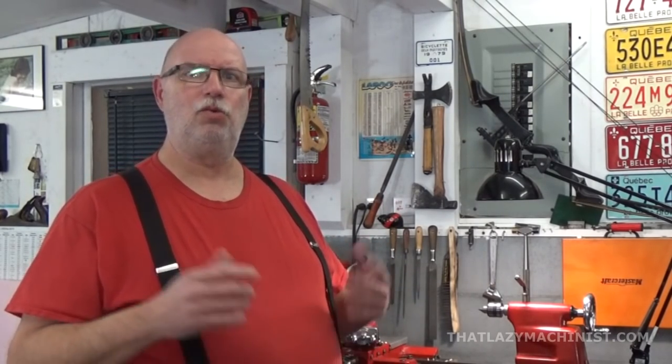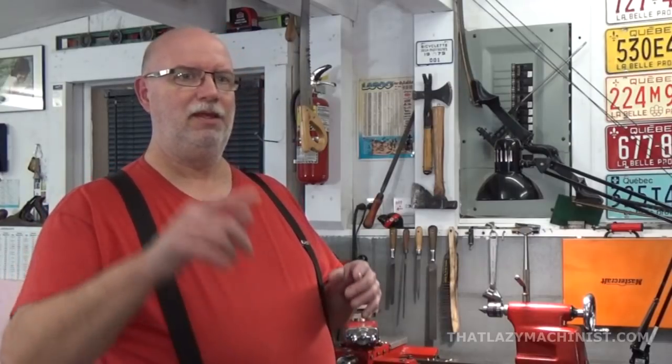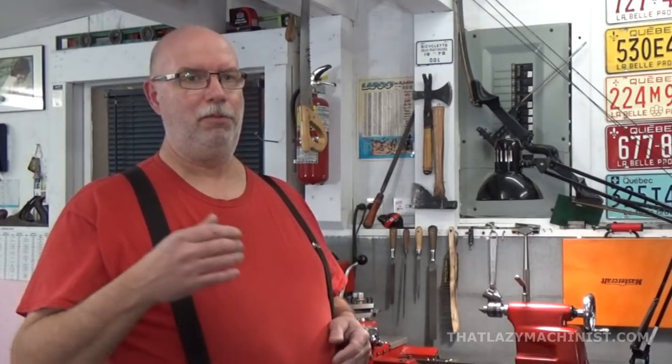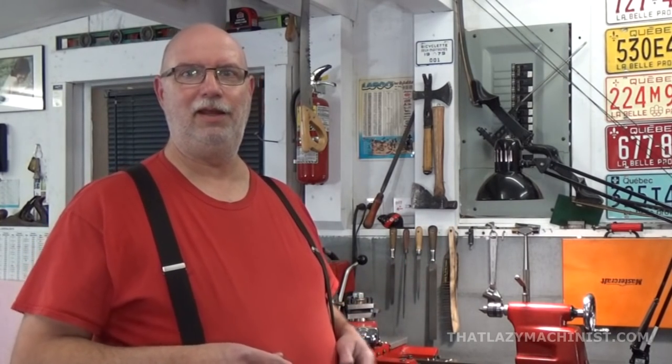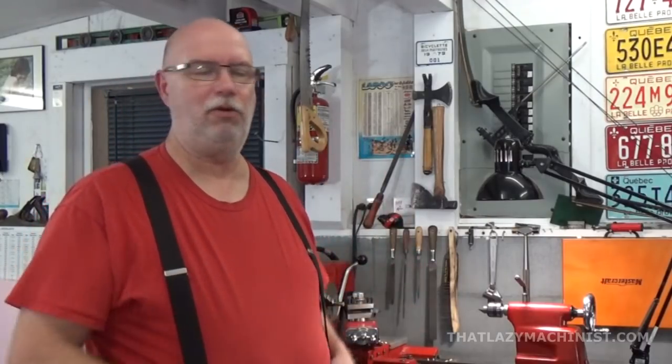And if that's the case, what most people will do is take a few passes until they get a complete diameter, and they'll start from there. But by that time, they're somewhere around, let's say, 498 thousandths of an inch. They're not at a 1/2 inch, a nice number I can remember that's easy to count from.